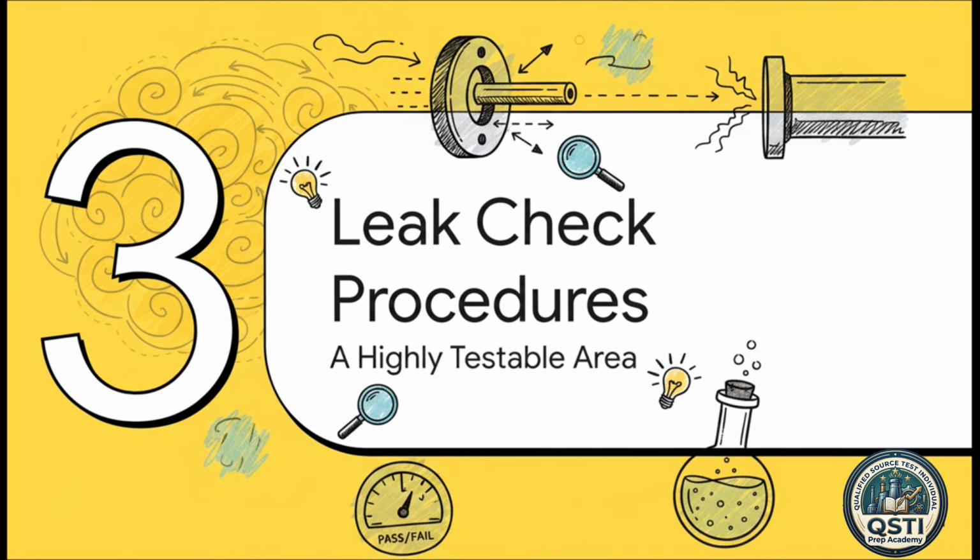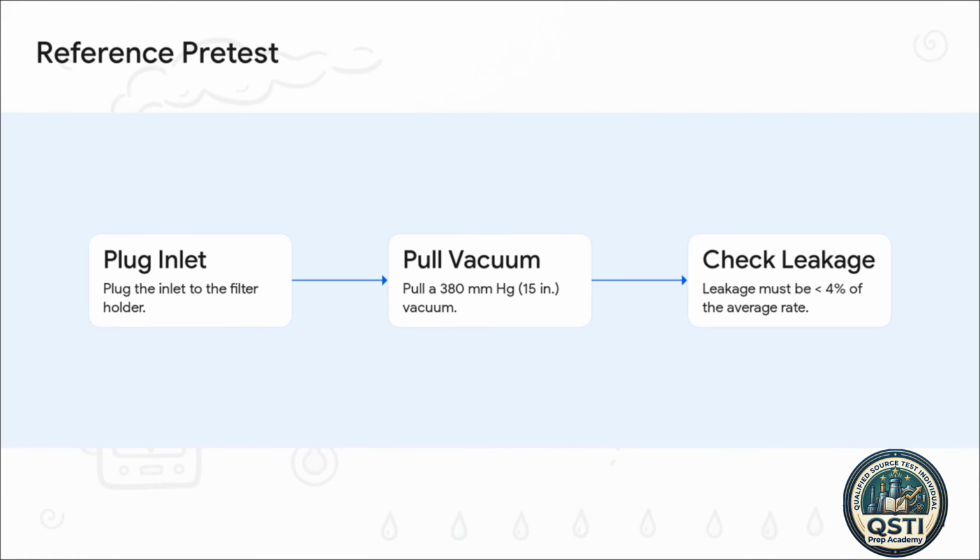This is a highly testable area. Seriously, a lot of people lose easy points on the QSTI right here, so pay close attention. Okay, so a pre-test leak check for the reference method is highly recommended. It's technically not strictly required by the baseline rule, but here's the absolute crucial point. If you do run one, your leakage rate cannot exceed 0.00057 cubic meters per minute at a 380 millimeter mercury vacuum or 4% of the average sampling rate, basically whichever is less. Make sure you memorize those numbers.